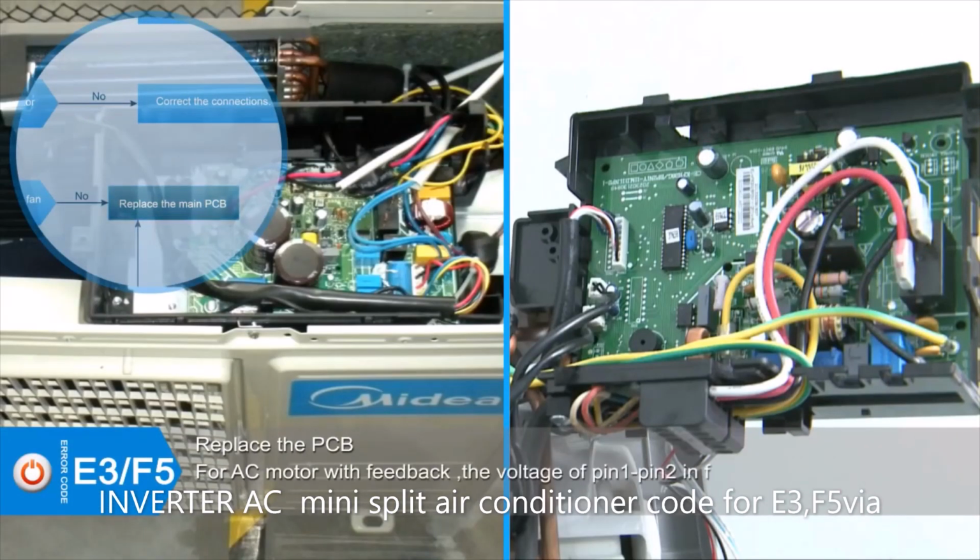Examination for main PCB board. AC motor with feedback. Turn the power on and set the unit as running in high-speed mode. 15 seconds later, measure the voltage of pin 1 to pin 2 in fan motor connector.